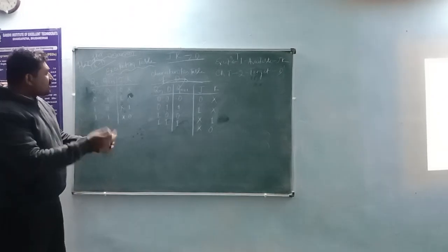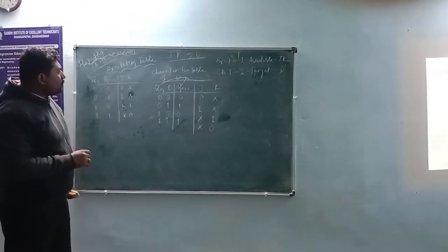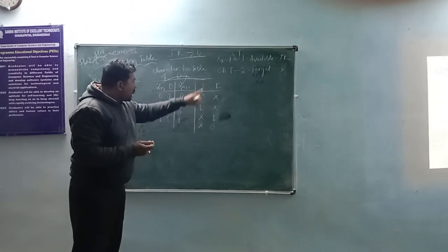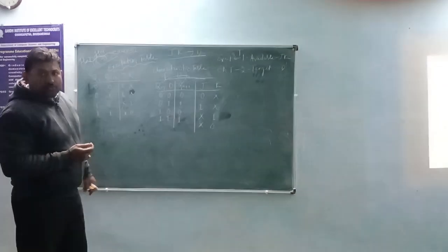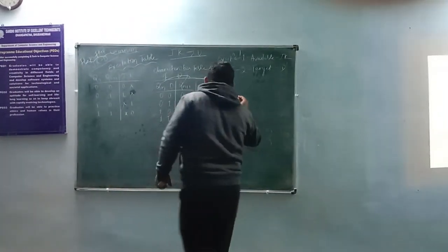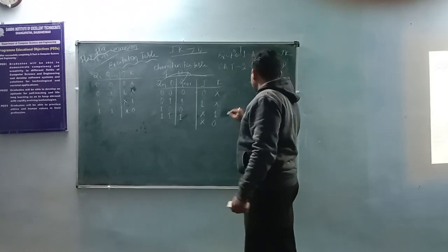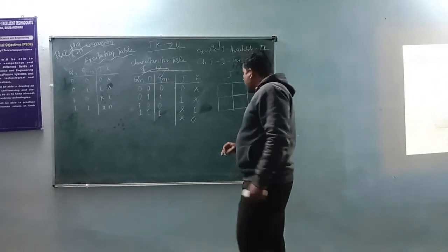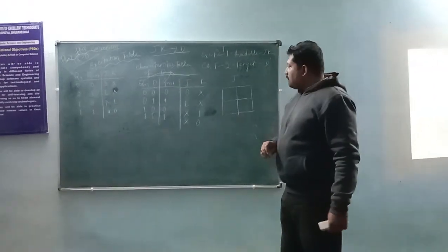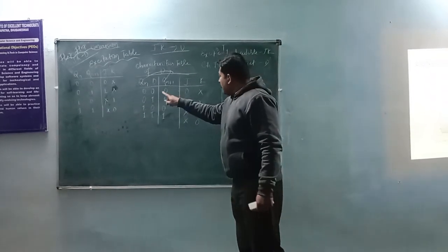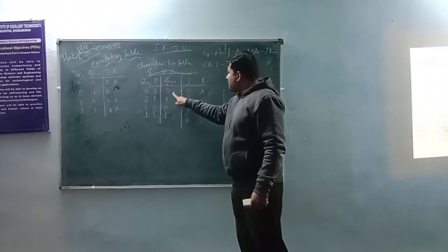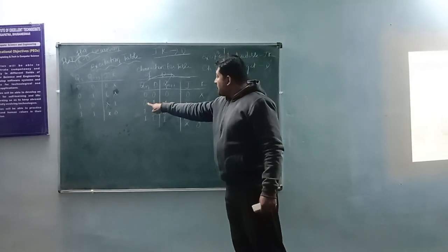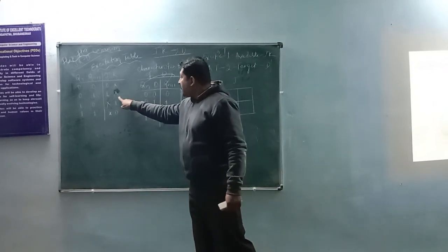Okay. So the next step is that we have to find out the circuit diagram for what J will have and what K will have. For that, again, what you can do is use the K-map. So we are going to have the K-map here for J. When we are targeting J to find out the circuit diagram and we are designing the K-map, you can see this one is a 4 variable K-map. And here many students go wrong by taking this characteristic table as Qn and Qn+1, because they are thinking this J value has been taken with reference to this Qn and Qn+1 and with reference to the excitation table of this one.